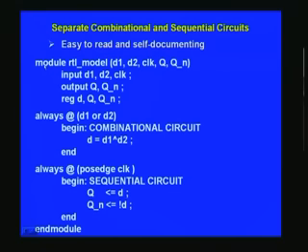And once you have identified it as a module, then you have to give a module name. For example, this is a model for RTL, so I will name it RTL underscore model. Like this you may have several such modules, but it is illegal to nest modules within modules. Nesting itself is putting a module within a module. For example, I cannot say somewhere here before the endmodule, call another module, say sequential module. I can't put another module. That is an illegal thing in Verilog coding as such.